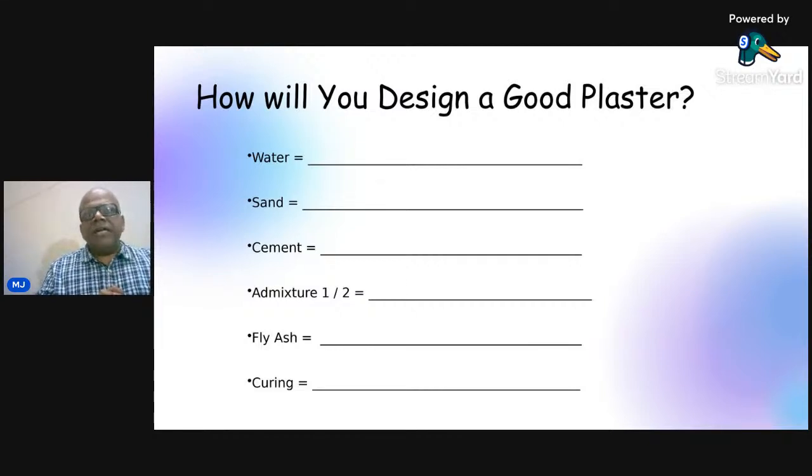So imagine you are doing your construction in a hot city like Ahmedabad, and you are doing your external plaster. It is the summer time, and because it is the summer time, you want to take extra precaution when you are doing the plaster. That this is my south wall and this is my west wall. So south and west, at this right angle joint, you should have Hessian cloth covering the plaster on both the sides.